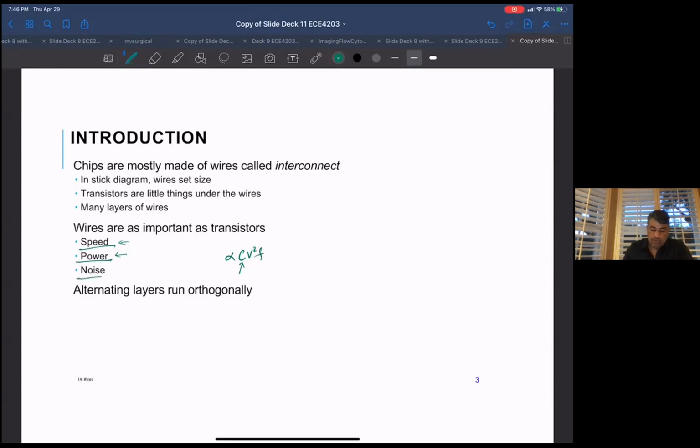And then the noise, we'll see, comes from capacitive coupling of lines to each other. Again, the dielectric between the metal lines is really thin, which means you have a lot of coupling capacitance. And to get the most efficiency, to get the most lines routed in your chip, you tend to be forced into making those lines very close to each other.